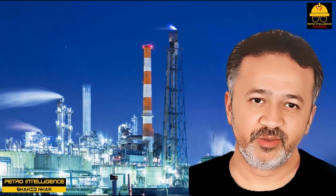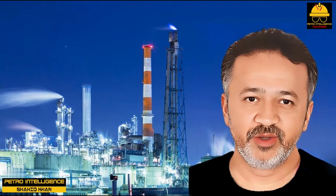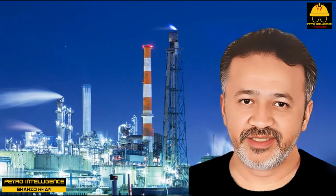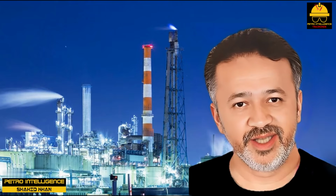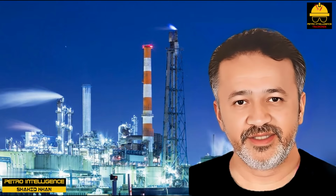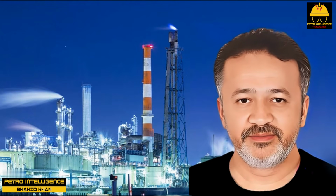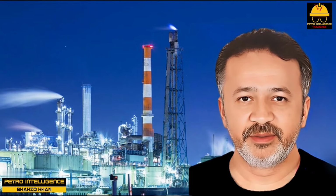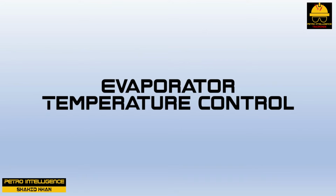Finally, the receiver will accumulate any non-condensable or hard-to-condense components that have accidentally entered the system. Air left in the vessels on startup is one such example. Traces of methane and ethane in a propane refrigerant system are another. These light vapors may be vented from the top of the receiver during normal operations.